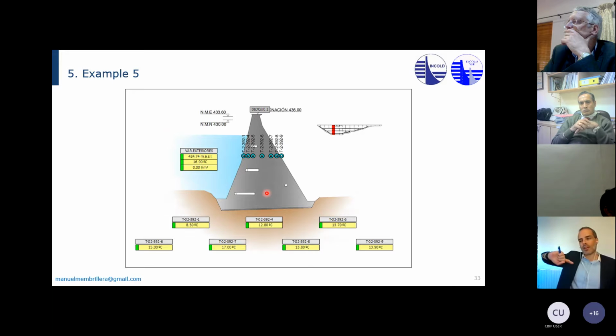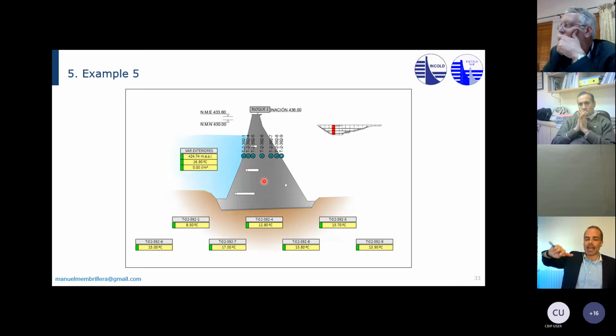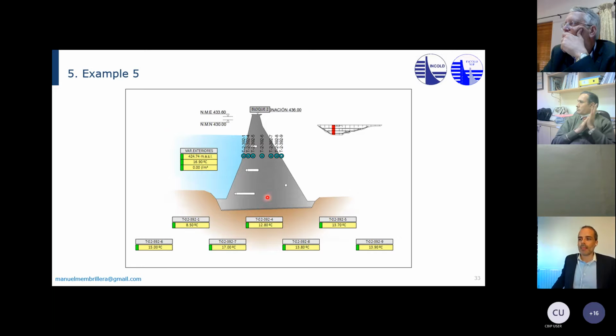As a matter of fact, another dam that I showed you in a previous presentation had a joint created during the construction here in the middle of the block, and this joint was grouted after the construction to give back the monolithicism of the structure, because it's such a massive dam.